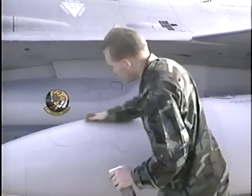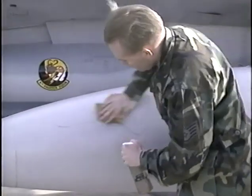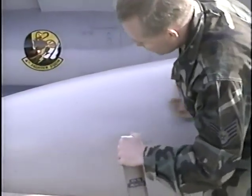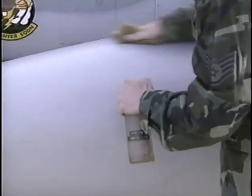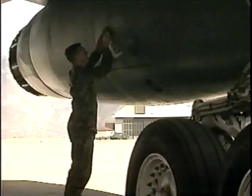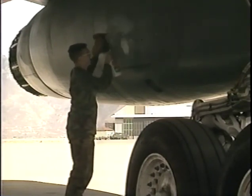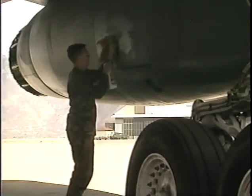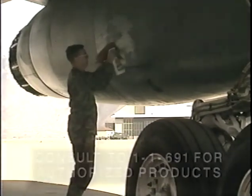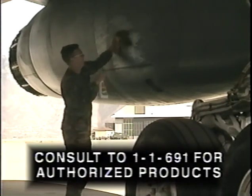Frequent wipe-downs are just as important as the scheduled washes and can actually cut down on the time you spend in the wash rack. When wiping down the aircraft, pay close attention to those areas prone to corrosion. One word of caution: the use of unauthorized cleaners can promote accelerated corrosion rates on metal surfaces. Use only those products approved for your particular aircraft.